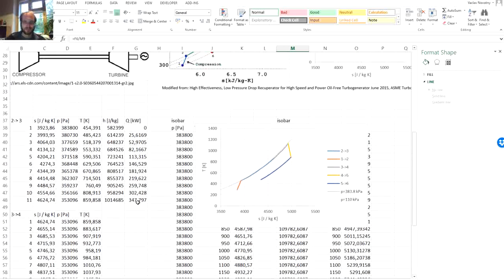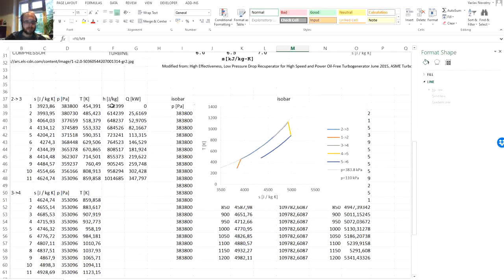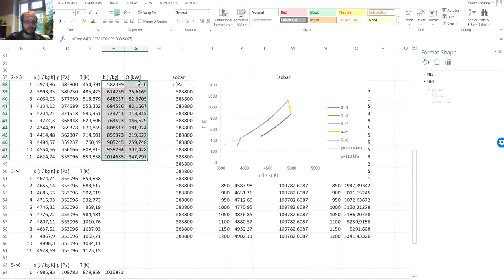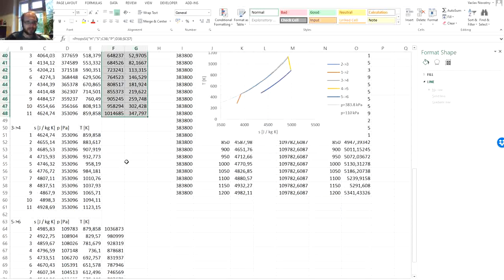This is the feature of the recuperator, and this, let's say, internal recycling of the heat is the way to get decent efficiency even at these low pressure ratios and not so high temperatures. Now the same procedure as we had between points 2 and 3 will also be applied between points 5 and 6. We already had the enthalpy.